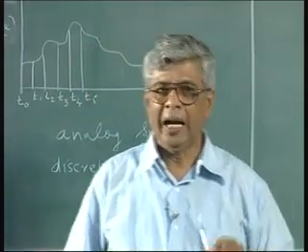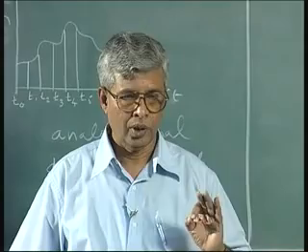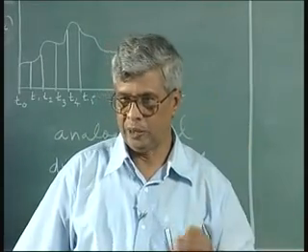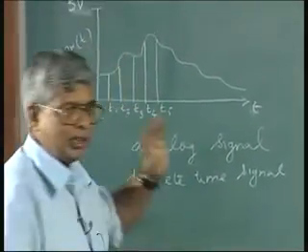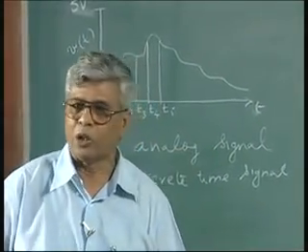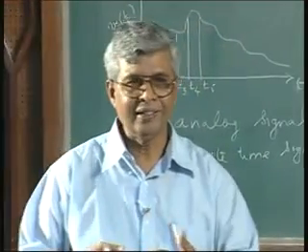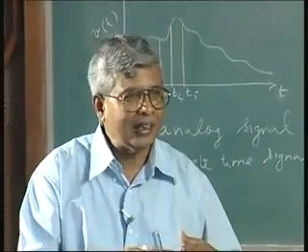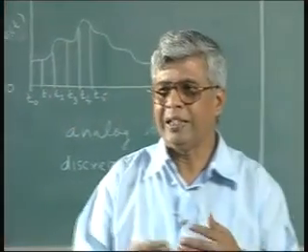I will only let the signal take a specific number of discrete levels. So 0 to 5 volts, even though the signal is allowed to vary, the input signal I have no control. The temperature variation, when I record it, I only record it as discrete levels, or when I process it, I only process those discrete levels. When I transmit it, I will only transmit those discrete levels.